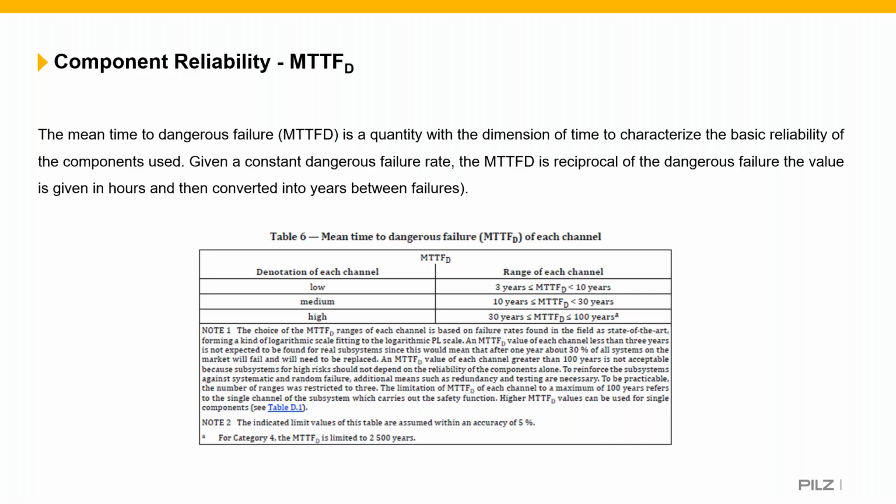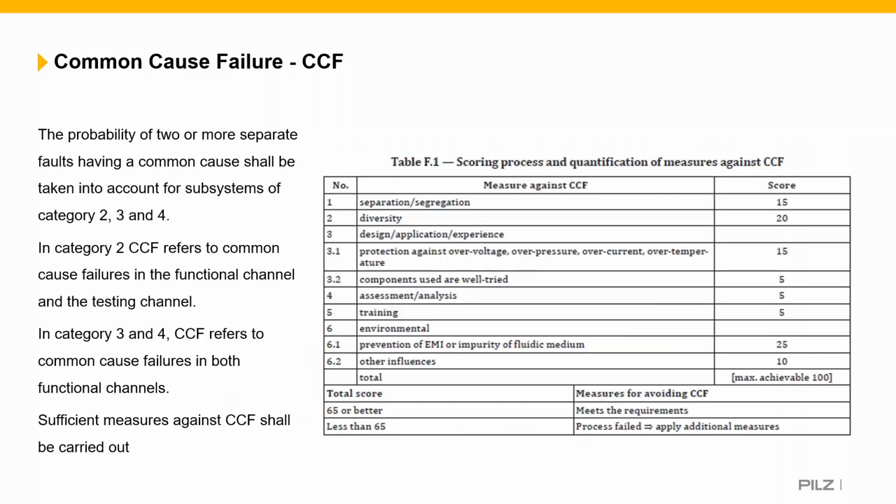But you would find that there was an accumulative effect in your verification where you would have various subsystems all capable of achieving performance level E, but the overall architecture was dropping down to D just due to the accumulative effect. So this wasn't deemed to be fair or accurate. So this capping was increased for very specific requirements where you have PL e Cat 4 devices or systems.